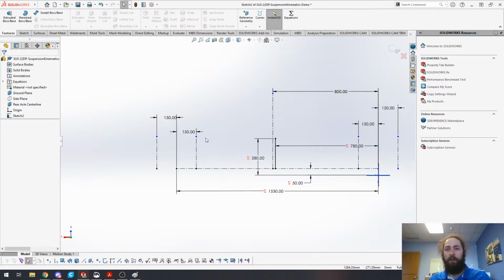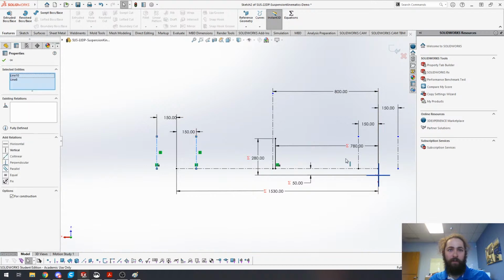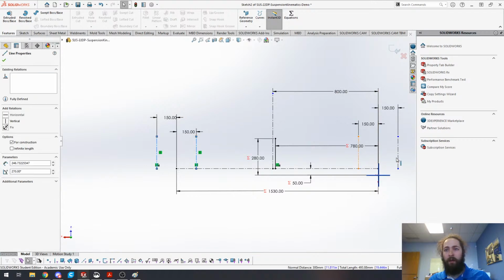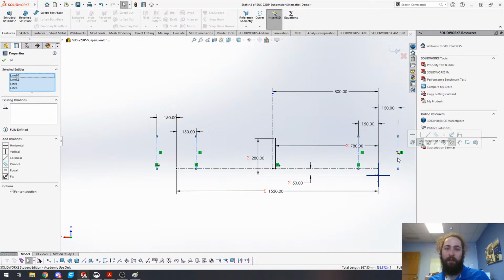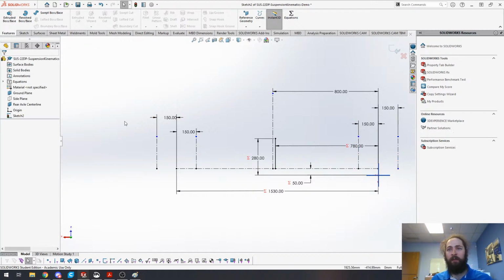But yeah, like I said, in this case, all we're doing is trying to create these 4 lines here that are going to be the inboard mounting points longitudinally. We're not really caring so much about width or height or anything like that. These are just kind of where it makes sense to plop down some vertical chassis members or any of that kind of stuff. In the rear, if we have a bulkhead, or if we're going off of the rear of the chassis, or where the diff plates are going to be, all that kind of stuff. This is all reference geometry for now.